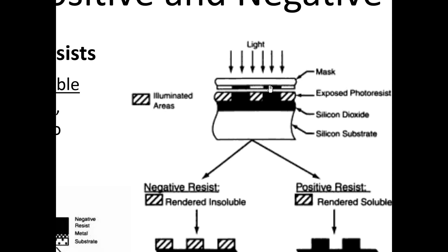You actually know the answer to this because we hinted at it in the previous slide. So you're not losing the parallel rays. Exactly. The closer the pattern is to the photoresist, the better off you are. So these patterns here will typically be made out of metal. There'll be a thin film of metal deposited on the mask, which itself is made of glass, but the opaque regions are metal, and the transparent regions have no metal on them. So the metal is actually facing the photoresist, so that you get sharper features.